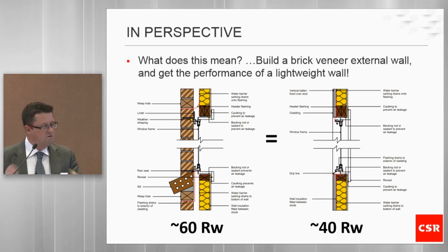We don't look at sealing all the gaps around the walls, floors, around the windows and doors. What we're actually paying for is a single skin lightweight wall, which achieves an Rw of 40. If we look at it like that, it's pretty obvious that we're just wasting money, right? And these are really simple measures.